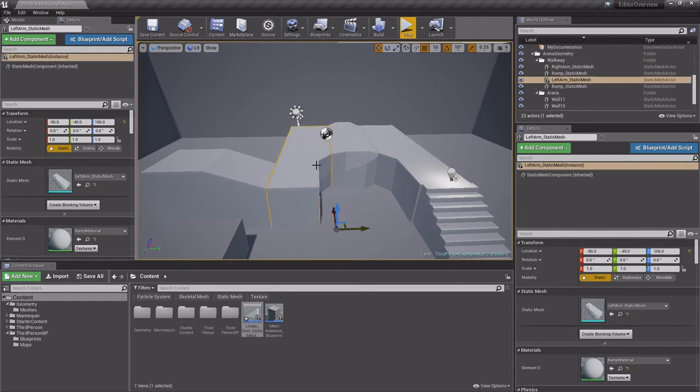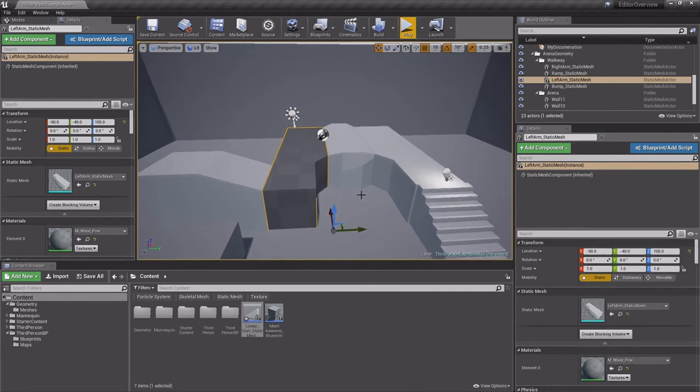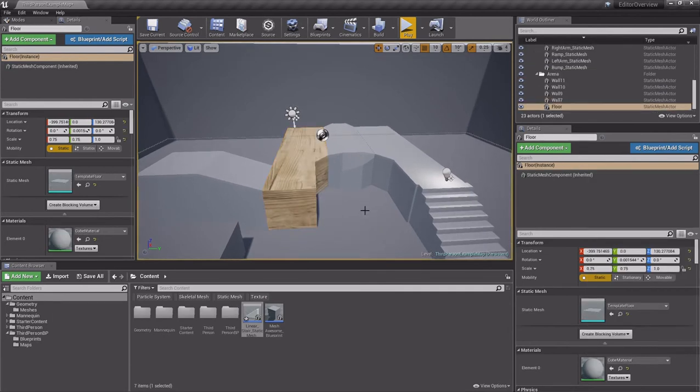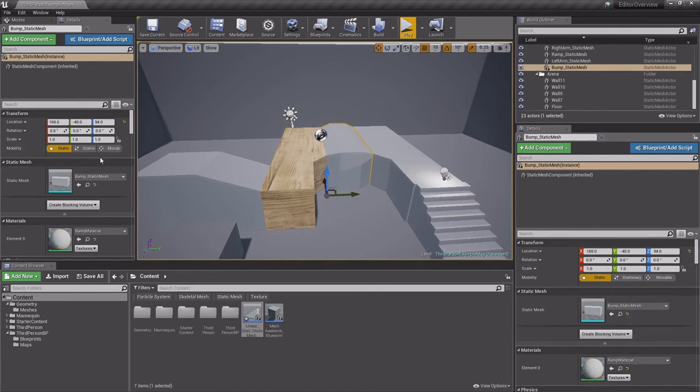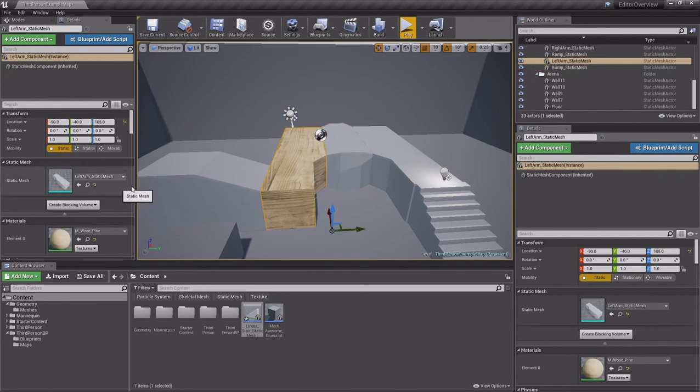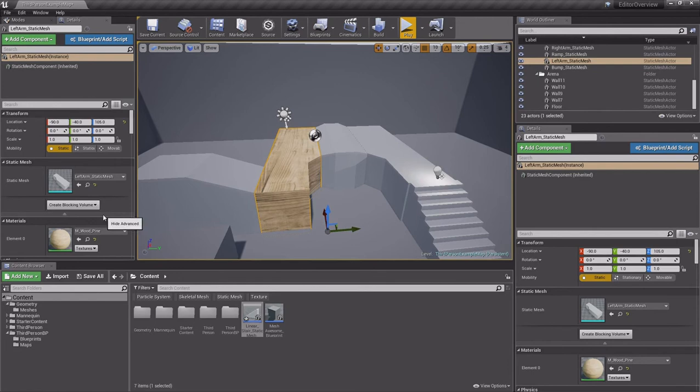Let's say we wanted to match materials. We have this item right here. We're going to go over here. I'm going to make this a pine material, and it's going to go ahead and compile it. And I like that. Now later on, I'm like, okay, well, I want to match some settings. I want to match some elements that may be different. Instead of clicking on one item, and you now have all these details, clicking on the other, clicking back, and maybe trying to figure out which details are different and which ones are the same, you can lock detail panels.